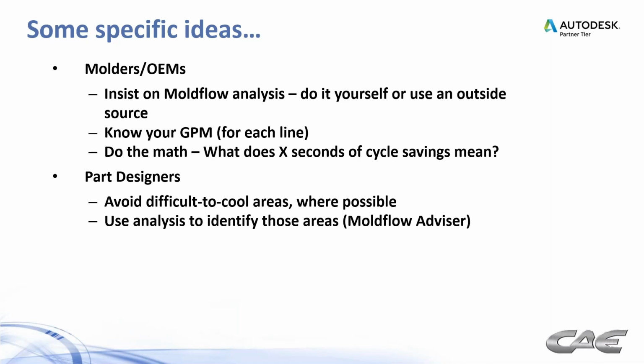And then, of course, use analysis to identify those areas. Everybody, in my opinion, should have some level of Moldflow on their desktop, even if it's just the Moldflow Advisor. Put that on your desktop. If you're a part designer, you can put your part design in there and very quickly identify what would be a red flag in terms of cooling.